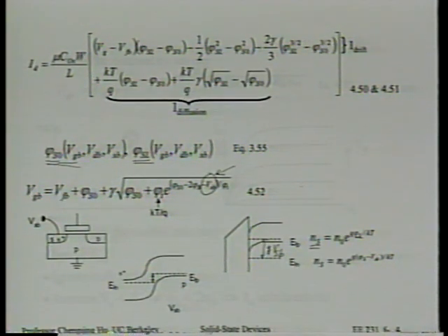So now we have two Fermi levels. So which of these two Fermi levels determines the ns, the electron concentration? If it's EFP, then the way I drew this energy band diagram should give us a decent density of electrons, maybe 10 to the 12s, 10 to the 14s, yeah?